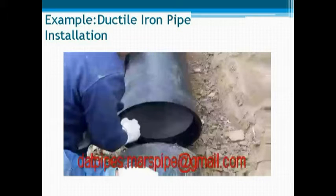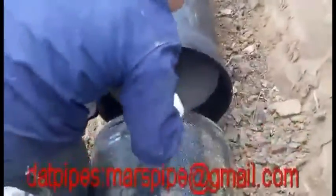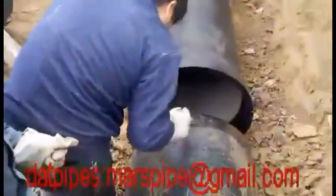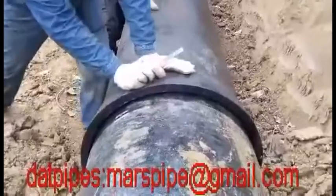First example is ductile iron pipe installation. As you can see, the gasket is already in place in the gasket seat. Before putting the gasket, make sure that the socket chamber is clean from any dust or dirt. Because the gasket is in place, the man is applying a lubricant around the spigot end. Then align the pipes and carefully push the pipe.